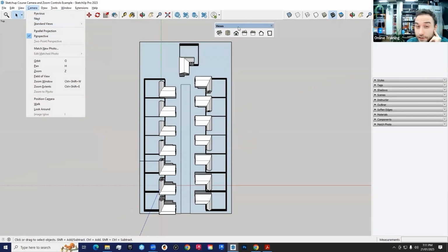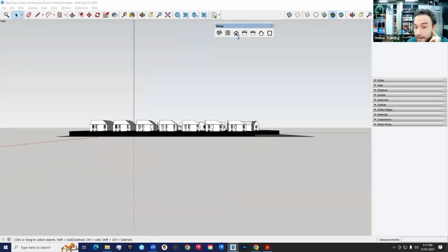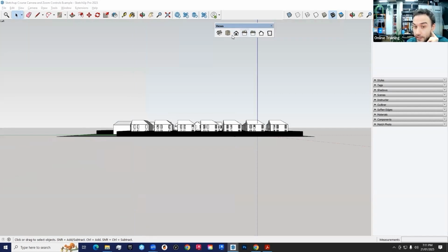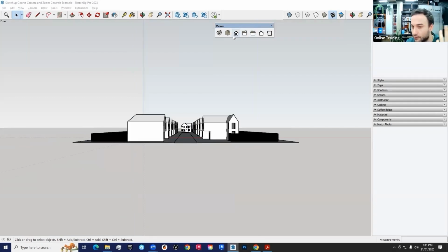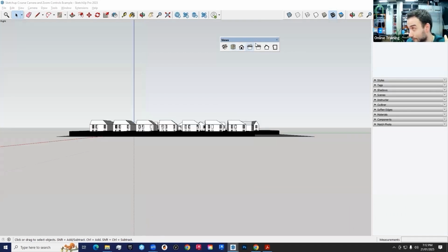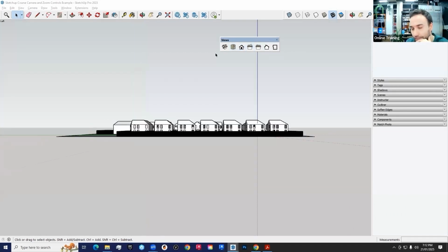And these are obviously very useful for presenting a document, but they're equally useful for drawing. If you're designing, let's say, a cabinet, you probably want to draw it from the front because that makes more sense than designing it from the top. So, depending on what you're designing, being in the correct view is going to be important. And I'm going to be talking about these a lot. So when we do a drawing exercise, I'll probably say switch to top view, and I'm talking about these house symbols, for example. There aren't any shortcuts by default attached to these,